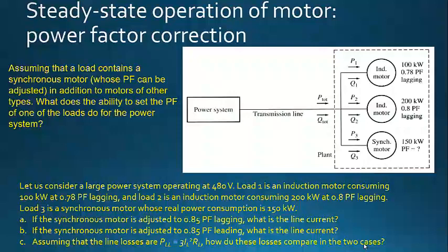Assuming that a load contains a synchronous motor whose power factor can be adjusted, in addition to motors of other types, such as an induction motor or whatever, what does the ability to set the power factor of one of the loads do for the power factor of the power system? That's basically what we are going to do.